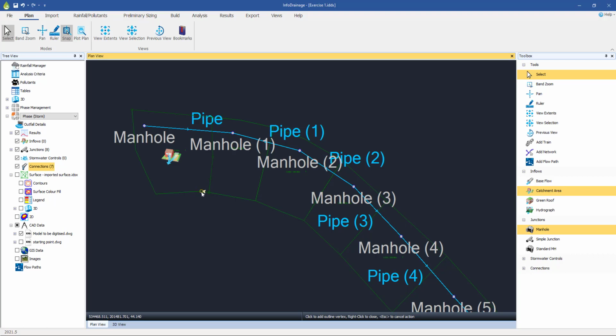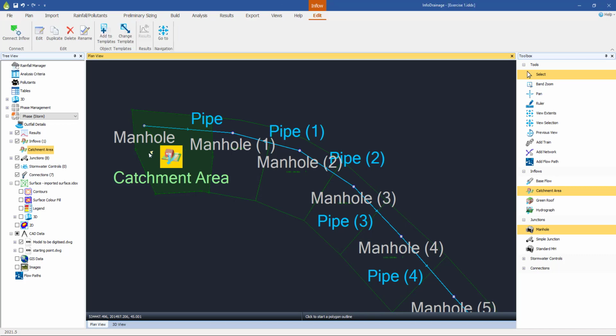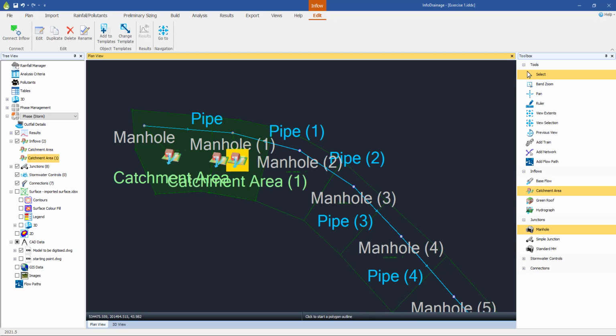There's a little one just there as well. There's one in that corner and there's one there. Now when you get to the last point, is it right click? Yes, it's right click and it then creates the catchment. Okay. And then we just carry on like that. So put the second one in. I'm going to start here in this top left. Again, it doesn't matter clockwise, anti-clockwise. There's another point there, one down, bottom right, bottom left, one there, and then right click to finish.